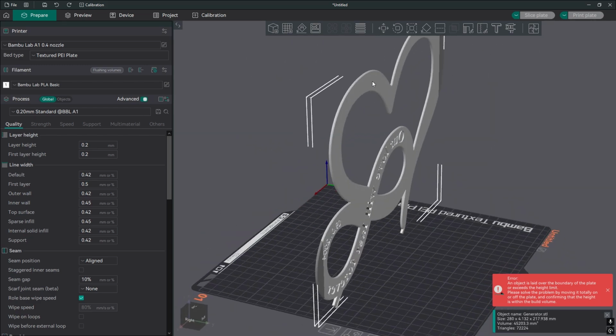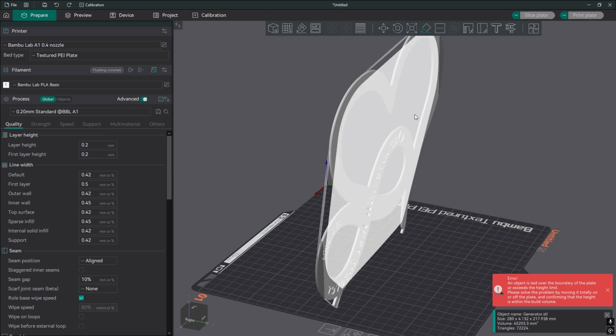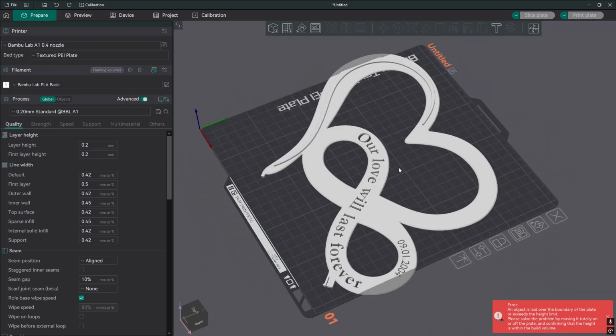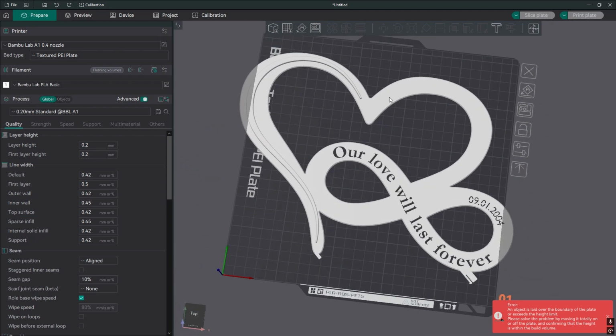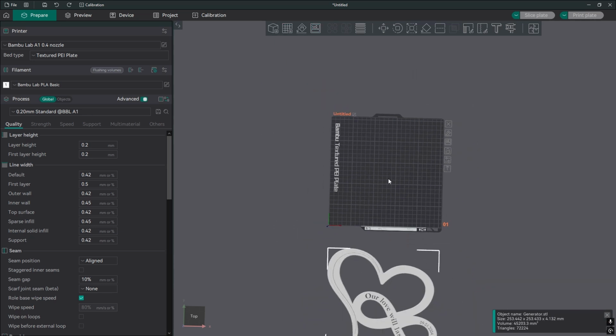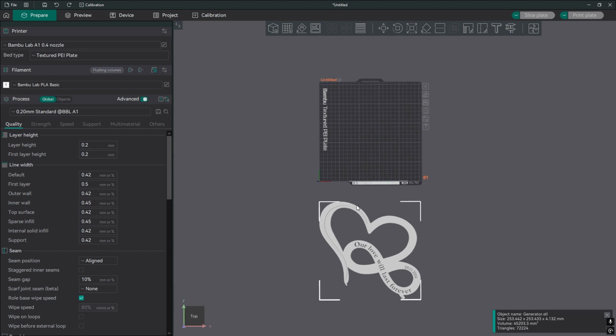So I click on the model, click on this button here, lay on face, and click the behind face. So this slicer will put the model facing up for me. After this, I click here, then click on this button here, arrange all objects, and I'll set all the settings this way: auto rotate for arrangement, and all the others unchecked, and click arrange. This will make my model with the correct rotation.